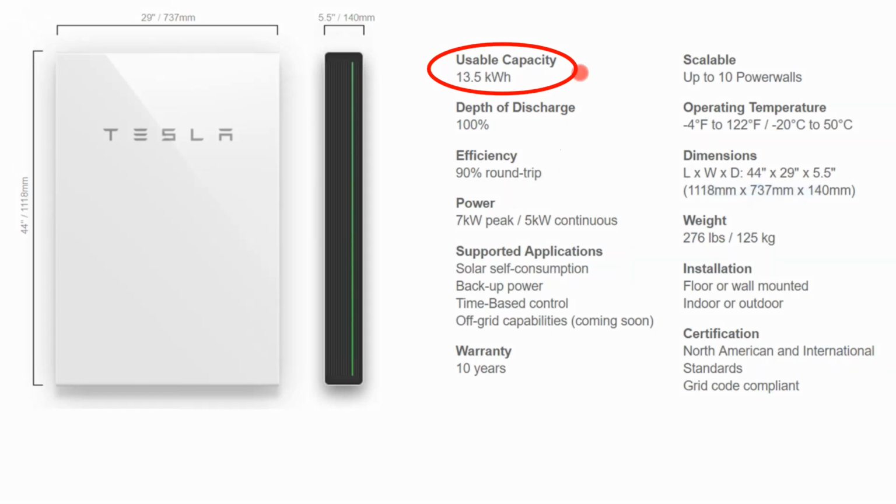Now, the Tesla Powerwall, for that matter, keeps a little bit of reserve capacity because technically, if you discharge a lithium-ion battery all the way down to zero, it literally won't charge back up again. You might be able to resurrect a lead acid, but lithium ion, if they fully discharge, they don't charge back up again. So it's almost like this subconscious weakness of lithium ion that they transfer onto lead acid.